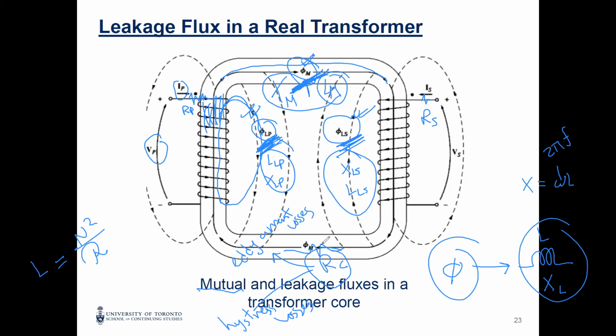As we said, R means losses, and usually it is converted to heat. If you put your hand on a loaded transformer, like the winding, you will find heat. This is because of the resistance of the winding, primary and secondary. The core is heated due to the eddy current losses.